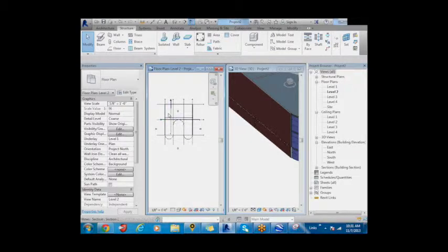Okay, so we wanted to make the point clear that you don't just typically put your shafts and stairway anywhere, like right in the middle. You basically want to place them depending on the egress, like the exit or fire exit. That's why in Y2E2, we have them located at opposite sides of the building close to the exit. That's typically what you do in most buildings.